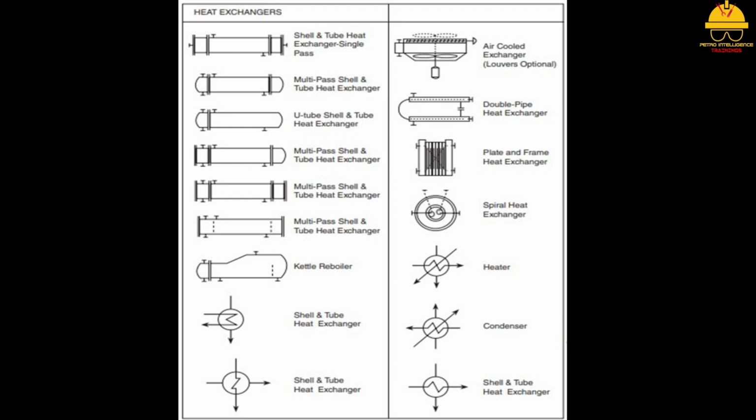A heat exchanger with an arrow drawn through the body illustrates whether the tube side flow is used to heat or cool the shell side fluid. The downward direction indicates heating, while the upward direction illustrates cooling. Heat exchangers come in a variety of designs from simple to complex.